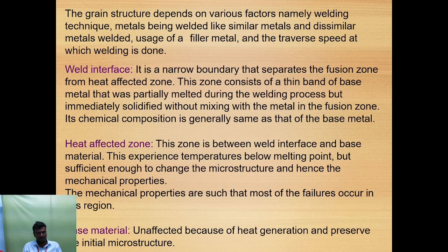And second is the weld interface. It is a narrow boundary that separates the fusion zone from the heat affected zone. This zone consists of a thin band of base metal that was partially melted during the welding process, but immediately solidified without mixing with the metal in the fusion zone. Its chemical composition is generally the same as that of the base metal.